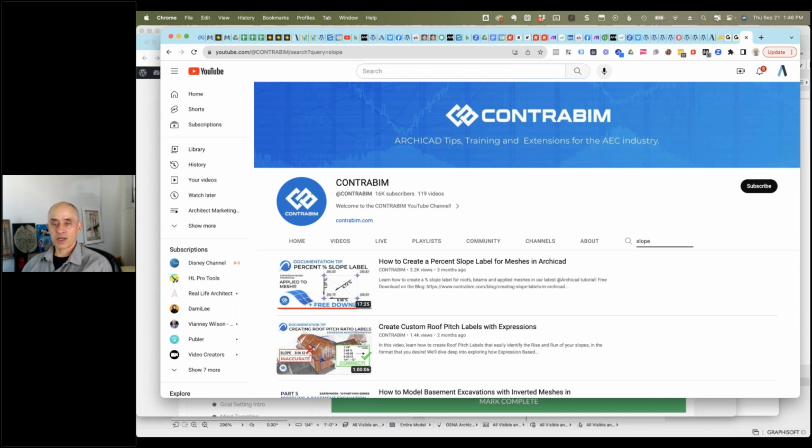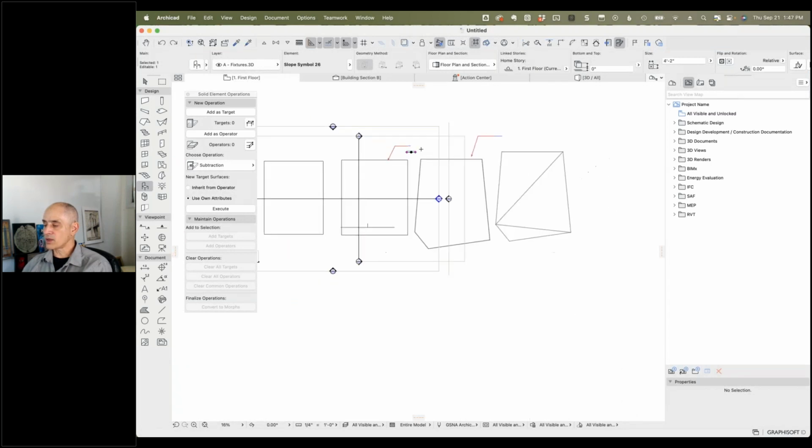All right, so I've been answering some questions and comments from Tom and David. Anything else on your side? I was going to show you one other thing, which was the union or the merging of stuff. If you wanted to have a flat bottom, like you're laying concrete on top of sand and gravel, but a sloped top, you certainly can do the mesh, because you can just raise points up. But if you did want to control the top slope for drainage, you could use a union approach, which I will show you here.